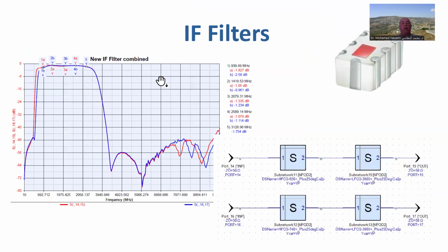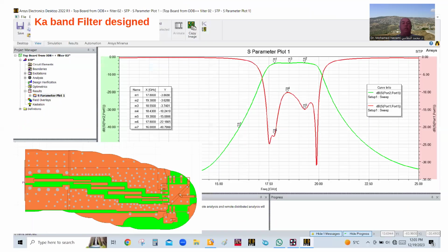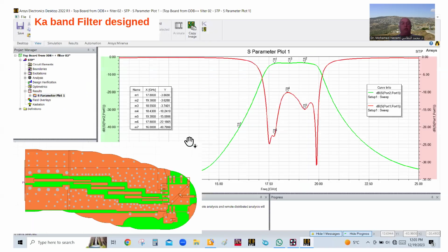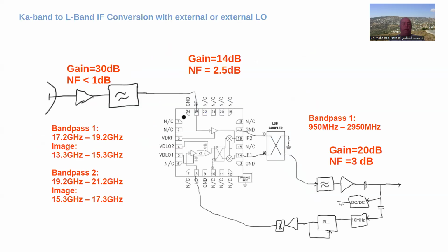Now, the other issue that I have is, of course, the 90-degree quadrature that I would need here in this mixer. By the way, I forgot to mention that the mixer model that I use in here is really based on the mixer model in the data sheet, which was measured or constructed using an external 90-degree hybrid. Okay, so I know this is a critical issue. For right now, I'm designing this based on the data sheet, which uses a specific 90-degree hybrid in here.